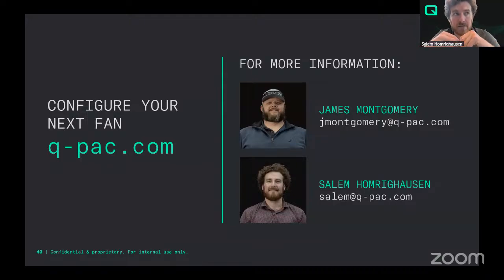Then there is your constant static pressure mode, where you can set this via a BACnet communication point, or just on the HMI on the front of the control panel. You specify a total static pressure for the air handler that it will maintain as VAV boxes open up and dampers close. Or you can tell it to maintain a constant volume of airflow. I'd caution against constant volume, because you don't want to blow out any ductwork, or if there are more dynamics with the cooling and heating loads of the building, you might want to move away from that mode. But those are the three automatic control modes available with the product.